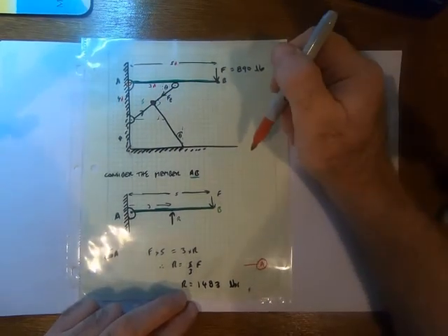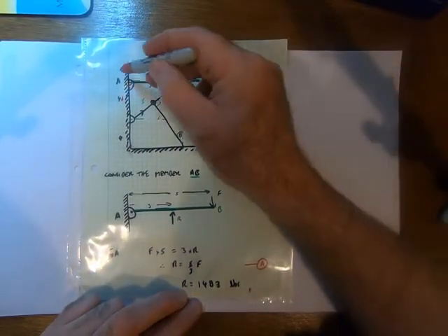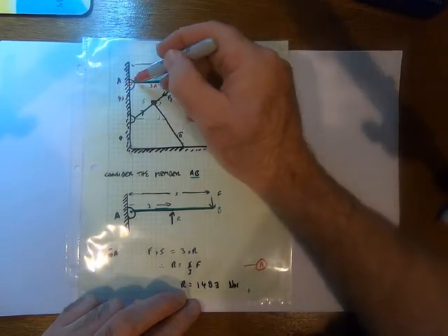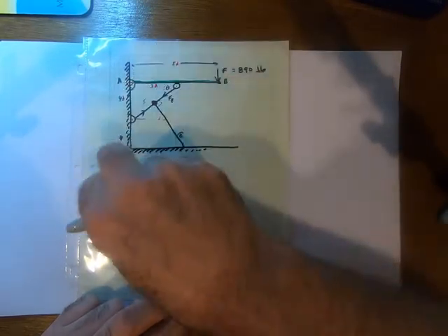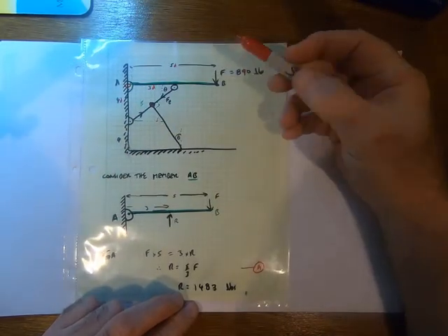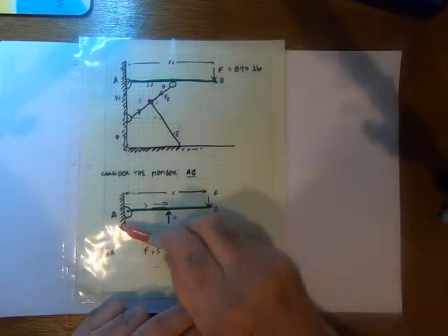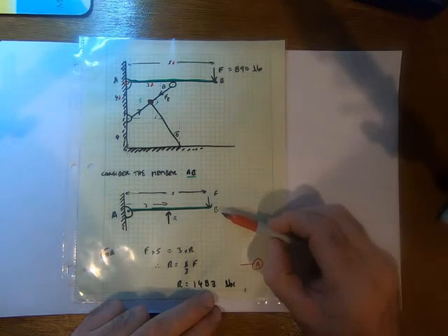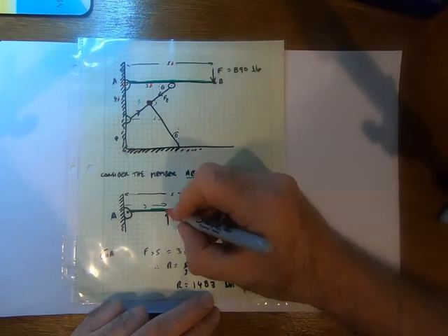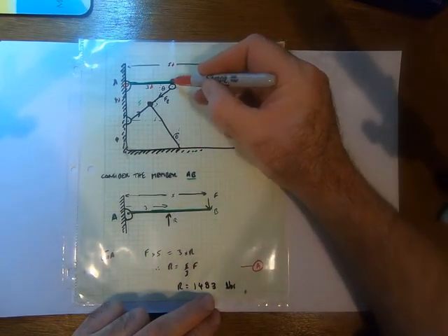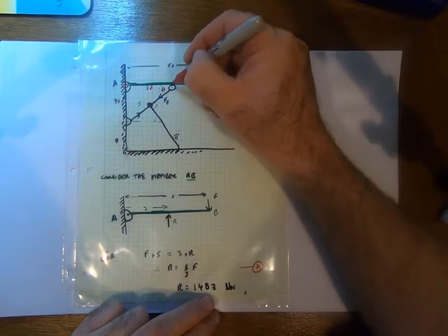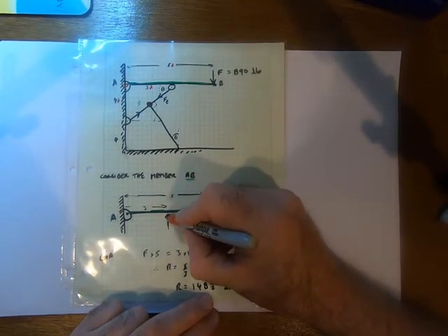So now I'm going to do the free body diagram. I'm going to start by looking at the cantilevered beam. So this thing here that's pinned, if this structure was taken away, this could spin around. So just by looking at this first, I'm going to draw it in isolation. So there is A and B. This roller is going to be able to exert no friction because it's a roller, so it can only provide a vertical force up. So that's what my force R is here.